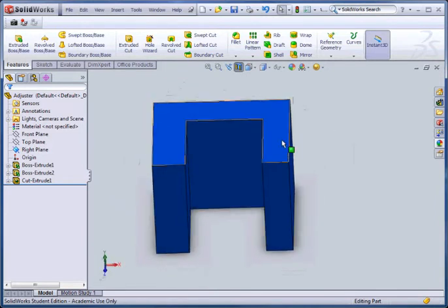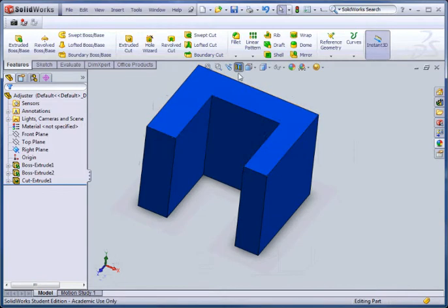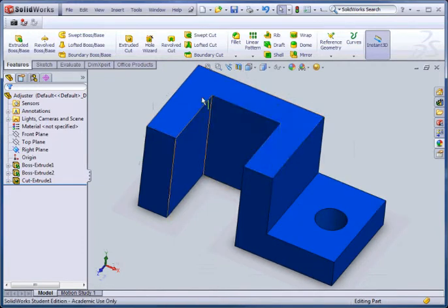It'll remain sliced in this section view unless I go up and I turn off section view. Notice how it's pushed down and it's gray? If I click on it, it'll get rid of that. It's no longer gray, and I have my full part.